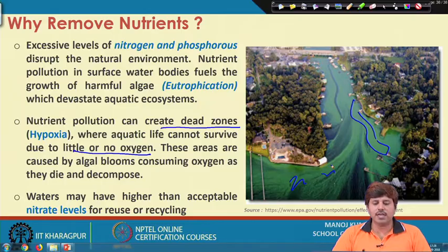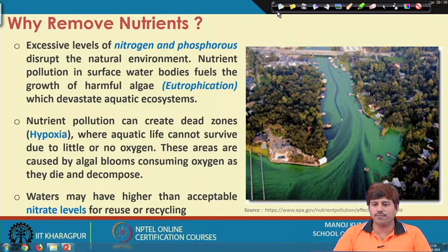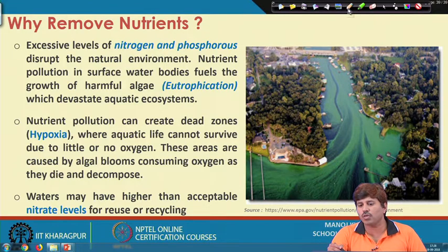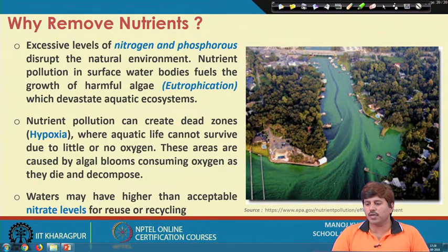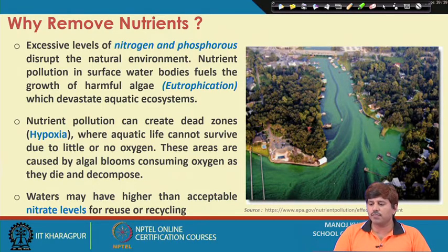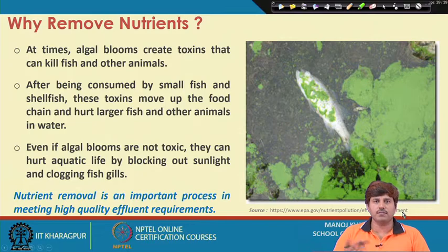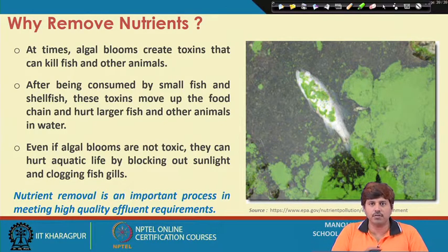Water may also have higher than acceptable nitrate levels. So, if somebody is willing to use this water for some purpose, the level of nitrate could be higher. Typically 10 milligram per liter is permitted, but it could be much higher than that, which can restrict the usage of this water for substantial purposes, particularly for domestic application or drinking water purposes.